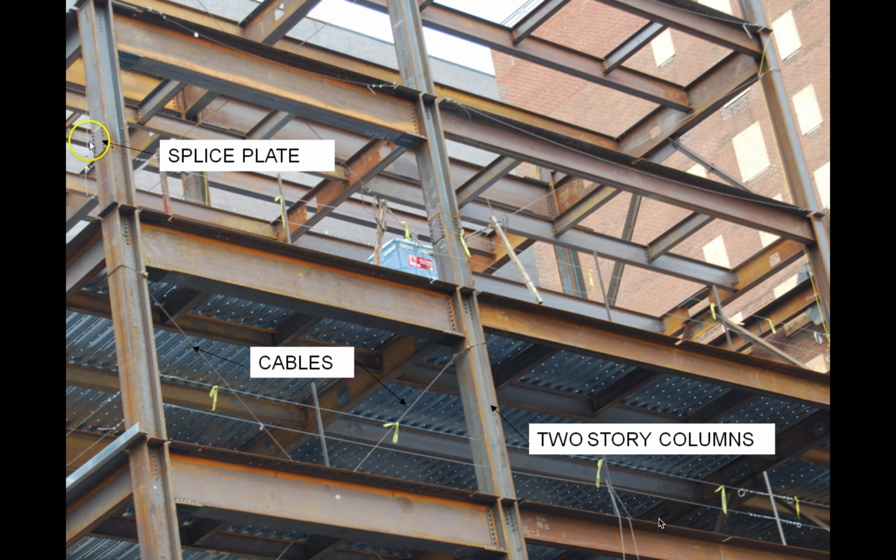Now a splice is, if you can see where it's called out, basically another sheet of steel or collar, so that when the 2 I-beams meet, we're not like gluing or welding them together. We're using plates, so that gives you the ability to tie them together using bolts, and you can keep the beam length short as long as you have a proper splice at each of those locations.